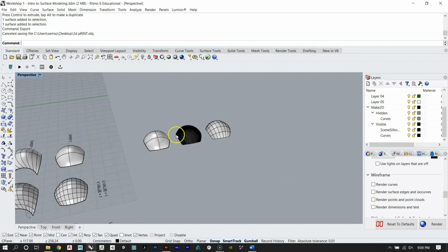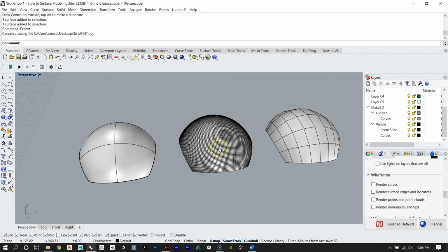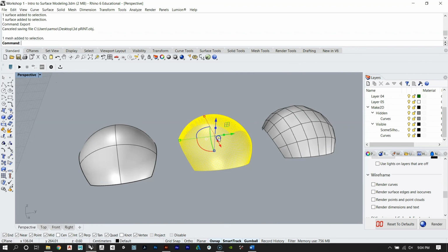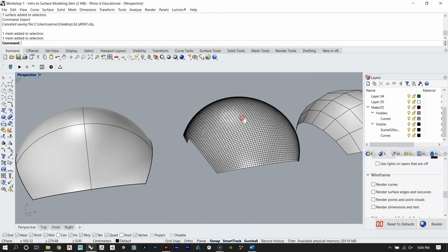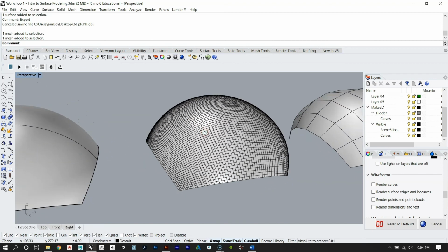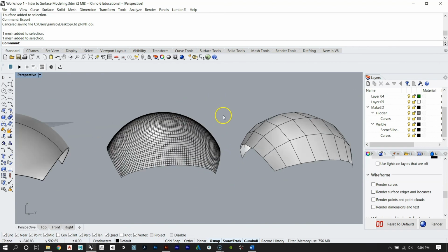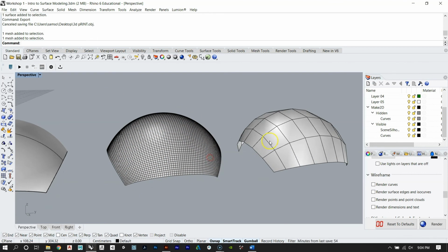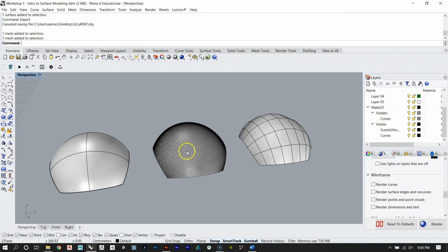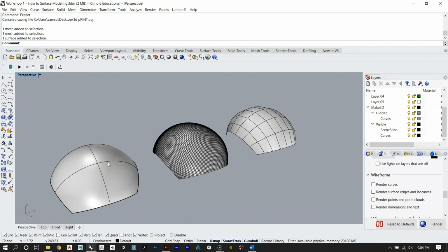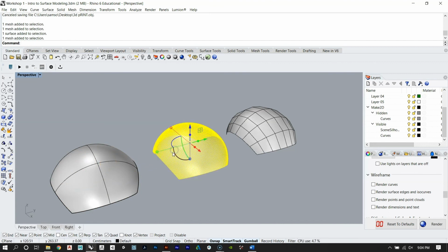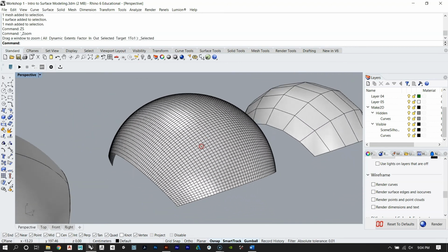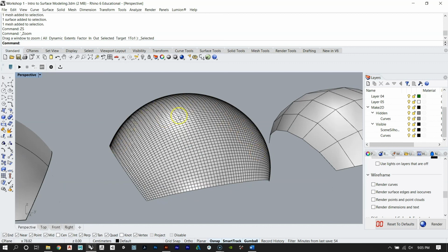Typically what I do is if I'm going to 3D print something, I convert it to a mesh in Rhino first, just so I can see what it's going to look like. And you want to do that because you want to pay attention to the density of that mesh. When you go to 3D print something, any curvature that you're 3D printing isn't actually curved. It's comprised of a series of faceted faces. The denser that curvature, or the denser that mesh, the smoother it will look. The less dense, the more faceted it's going to look. So you want to make sure that when you're exporting out your models or your NURB surfaces from Rhino for 3D printing, that you're getting a nice high dense mesh, so that you've got some nice clean curvature for 3D printing.